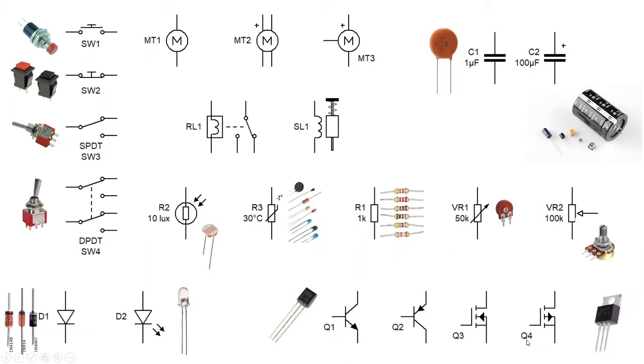But transistors and MOSFETs are basically electronic switches. So they'll take a very small current and amplify it and switch on a much bigger current. Now that can be used for literally amplifying a little signal or a sound, or making a decision from a very small microprocessor delivering a very small output current, which can be used to switch on something a bit more useful, like an LED or a mechanical switch, which are these things here called relays. Okay, so these here are outputs, and there's going to be another video further down the line where we'll cover these in more detail.